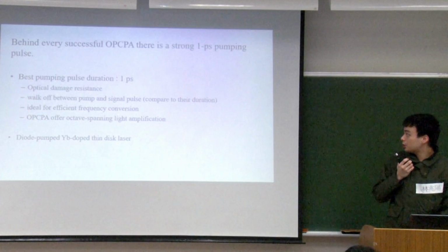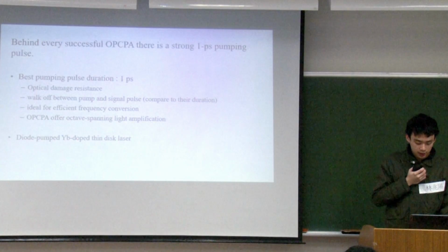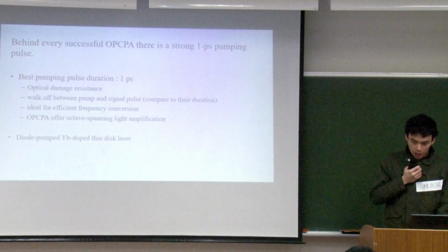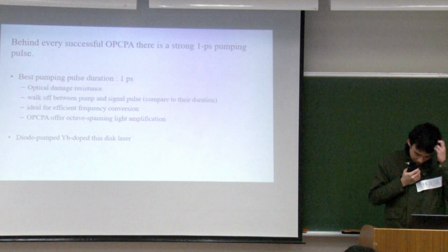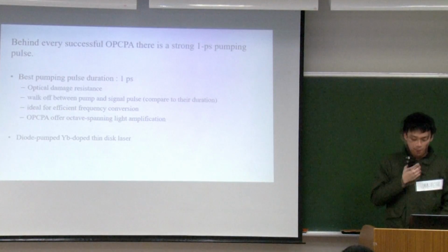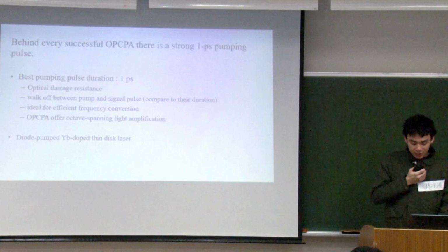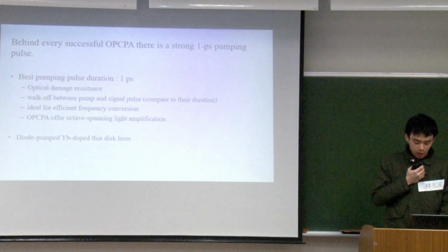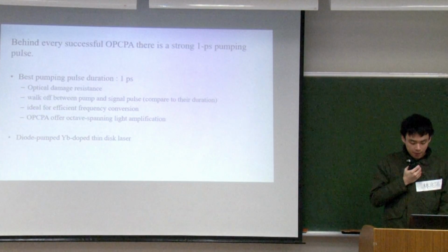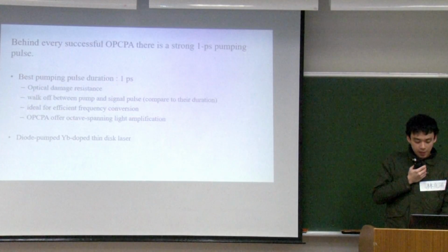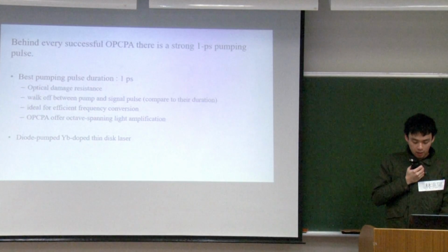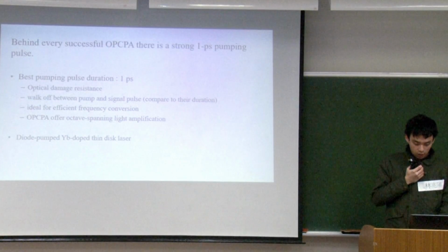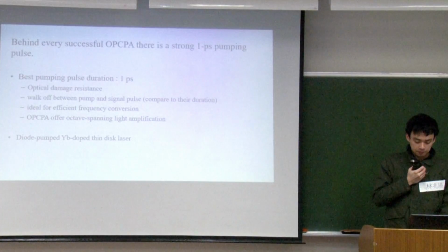Since the third generation FST is based on OPCPA, if we want our system to perform in its best form, we need a better pumping system. The best pumping pulse duration is on the order of 1 picosecond. And a 1 picosecond pumping pulse is the optimized choice, considering the trade-off between optical damage resistance and the walk-off between pump and signal pulses.